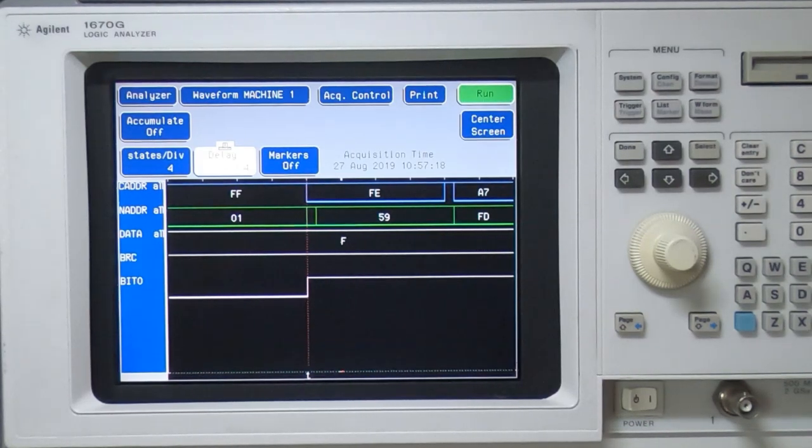So what I'll do now is take the ROM out of the board. We'll attempt to read it, and if we can confirm it's faulty, all well and good, but I'll replace it anyway, and hopefully the code that I have is correct, and then we'll get the board reinstalled, get the analyzer back on and see if things have improved at all.